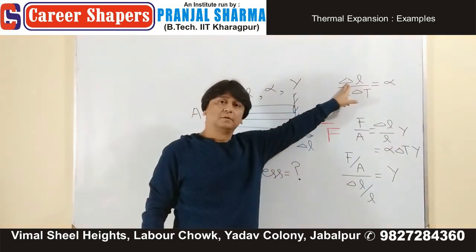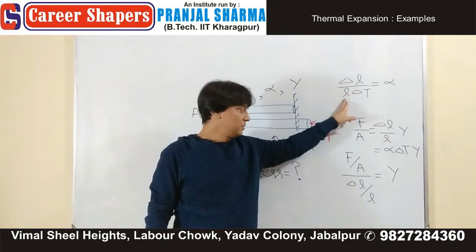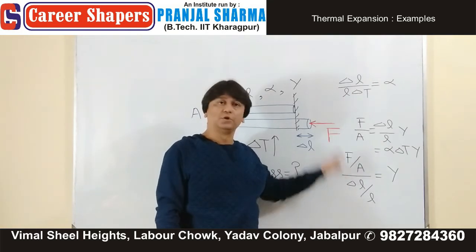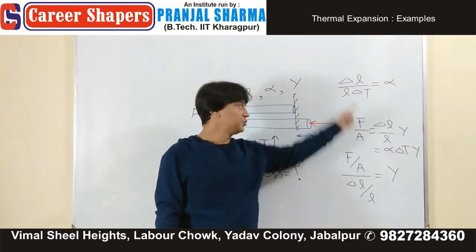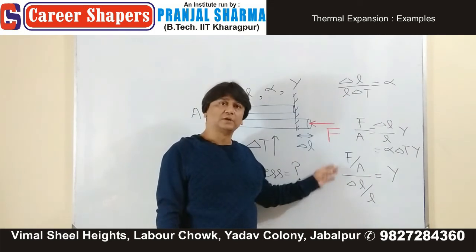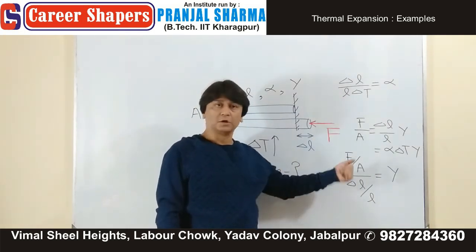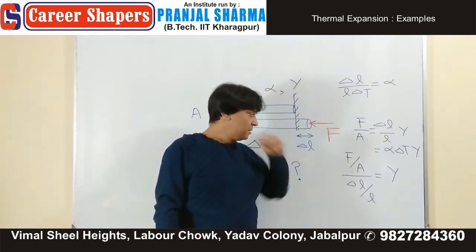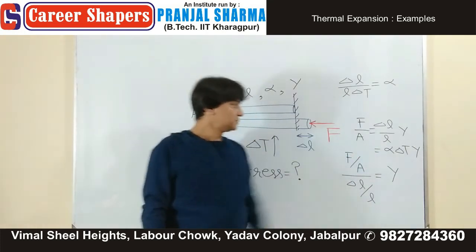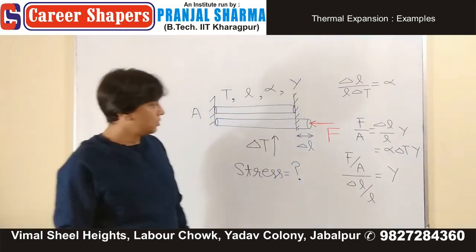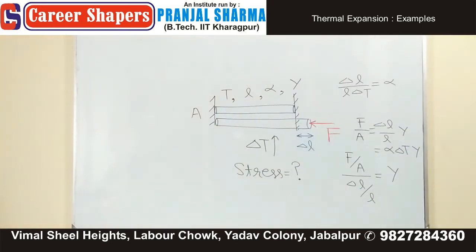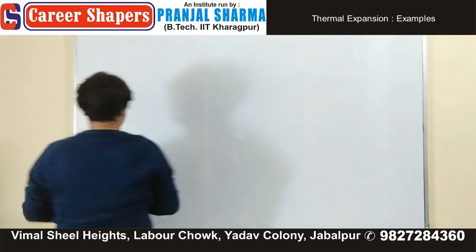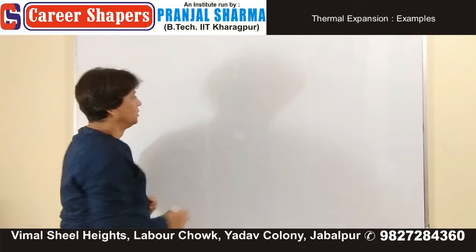Change in length divided by length is strain, and we have found the value of strain using what? Coefficient of linear expansion, and then using stress upon strain, which is a constant called Young's modulus, we can easily find the value of the stress. Note down this.